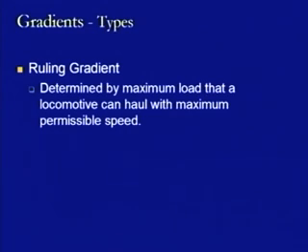So, whatever value comes for that gradient in terms of so much rise or fall with respect to the horizontal distance moved, that is going to be the ruling gradient. Looking at these performance features of the geometrics as well as of the locomotive characteristics, this is defined as the design gradient for any railway track. So, most railway tracks which need to be designed should try to keep the gradients within the ruling gradient condition.